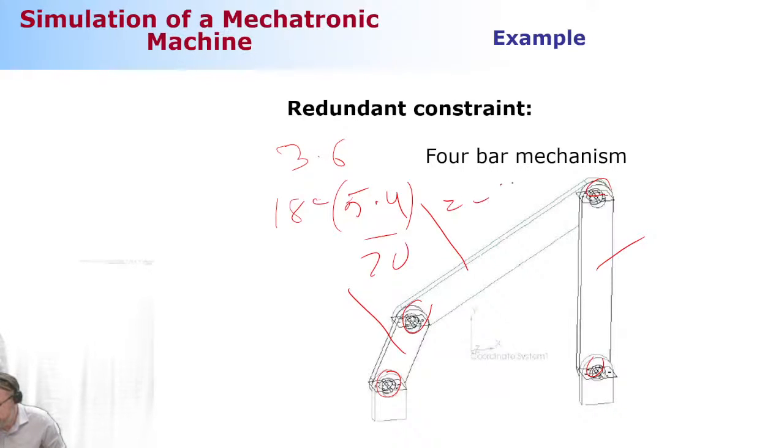So it's minus 2 degrees of freedom because it's redundant. They are eliminating the same motion possibilities. Like this revolute joint and this revolute joint, they eliminate the motion in the off-plane direction, so that's why they are redundant. You can easily end up with a redundant system, particularly in 3-dimensional space. So the better modeling practice would be taking this away, using, for example, an in-plane primitive constraint instead.